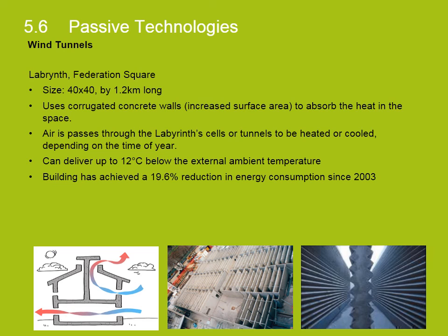As the air is passed through the labyrinth cells or tunnels, it is heated or cooled depending on the time of year. This system can deliver up to 12 degrees difference between internal and external ambient temperature. Since 2003, the building has achieved a 19.6% reduction in energy consumption.